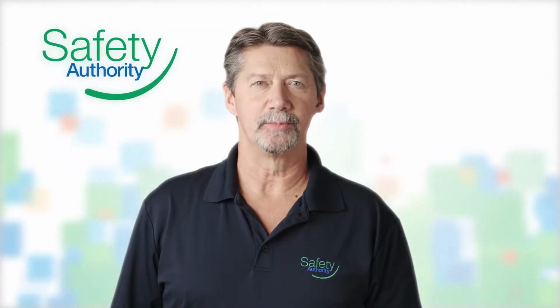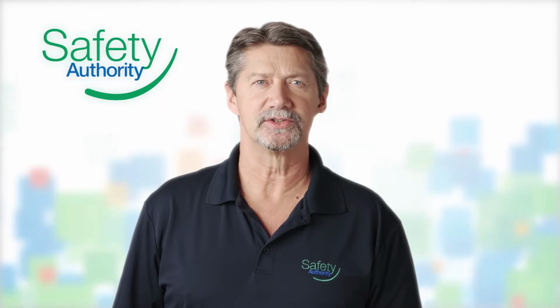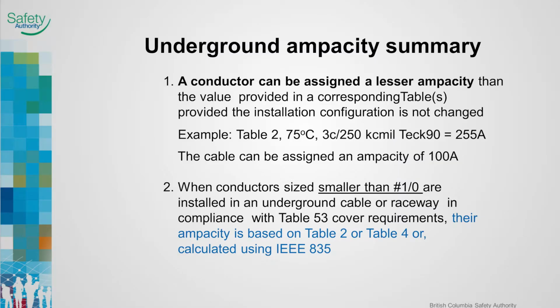The changes discussed about copper conductors in Subrule 1 also apply to aluminum conductors in Subrule 2. The ampacity assigned or calculated for a given conductor is the maximum ampacity. A lesser ampacity may be assigned to that conductor. 4-004-1F allows conductors sized smaller than 1/0 and installed underground to have an ampacity based on Tables 2 or 4, based on the marked termination temperature rating.